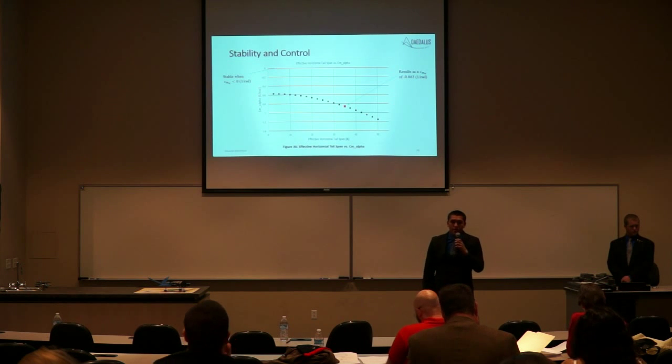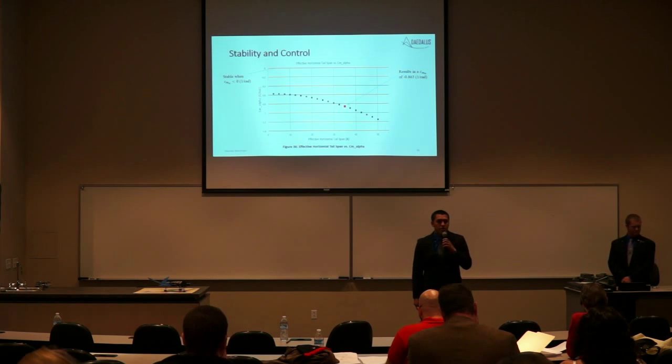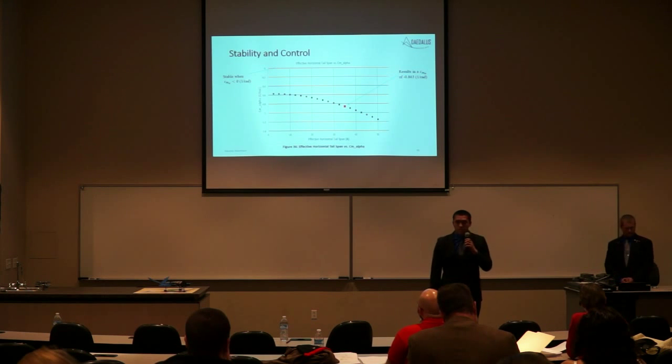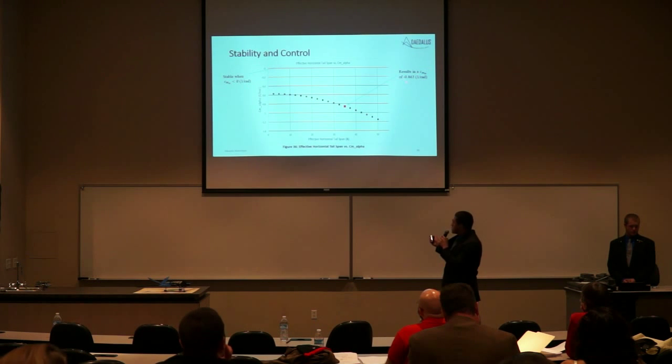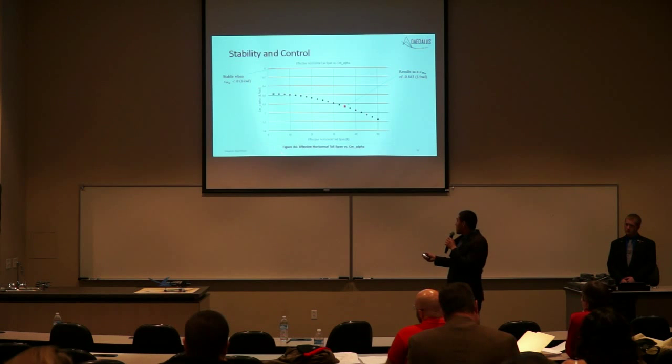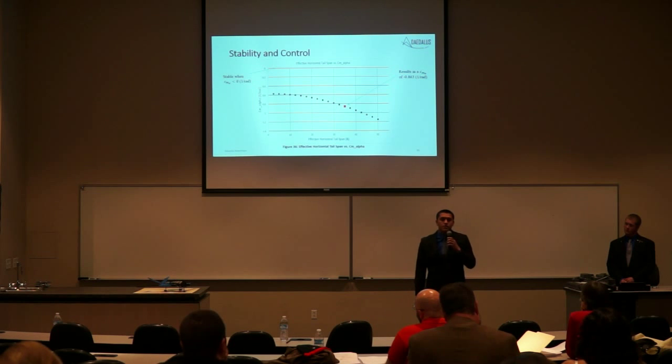When sizing the VTOL of the YB-3, it was essential to maintain the 30-degree dihedral due to LO purposes. As a result, it was only essential to size the effective horizontal tailspan, which corresponded to a CM alpha of negative 0.863 per radian. This is at a horizontal tailspan of 35 feet, and for any value that is less than 0 for CM alpha, it is considered stable. Note that any value for effective horizontal tailspan results in a stable aircraft. Therefore, the YB-3 is inherently longitudinally stable.